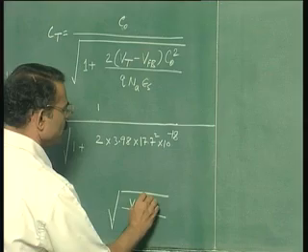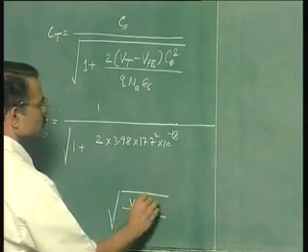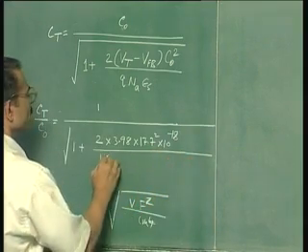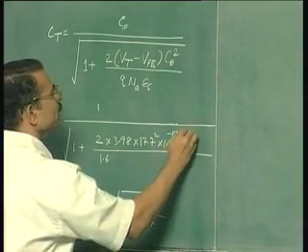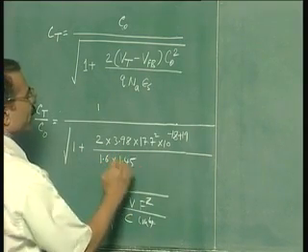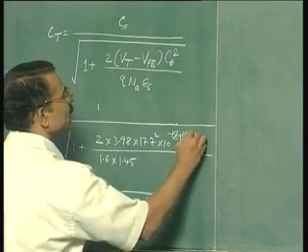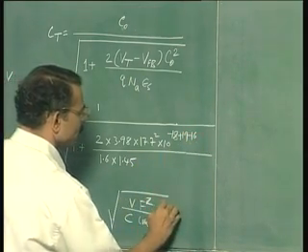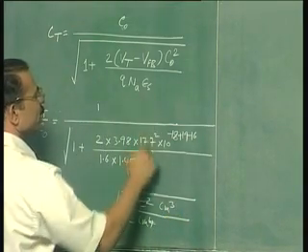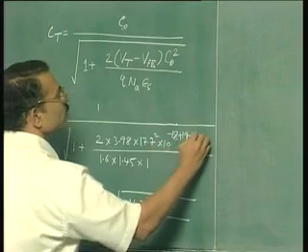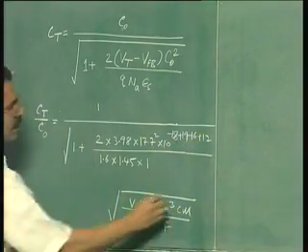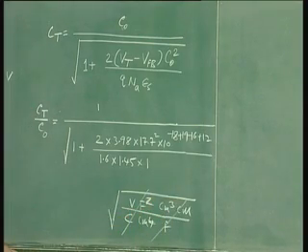So farad square per centimeter 4 divided by Q is 1.6 into 10 power minus 19 coulombs. So minus 19 goes here as plus 19 coulombs into doping is 1.45 into 10 power 16, that goes as minus 16 over there centimeter cube, and finally epsilon s, this is 10 power minus 12 farad per centimeter. So that goes as 10 power 12 over there farad centimeter. You check that all these cancel and you get a dimensionless quantity.